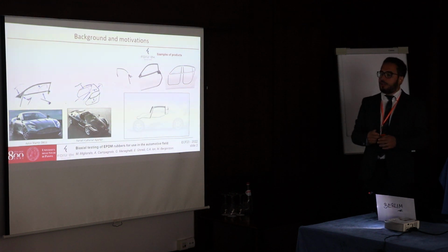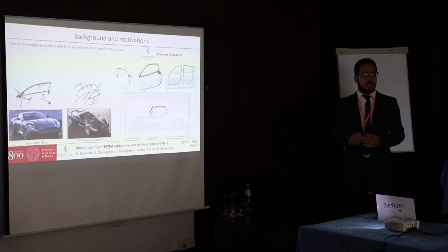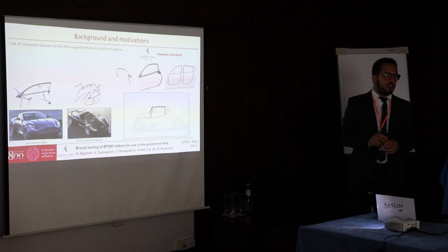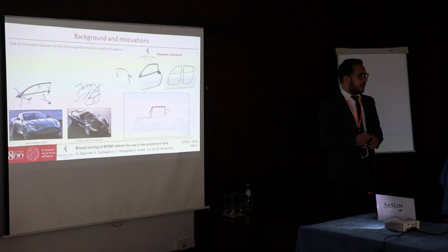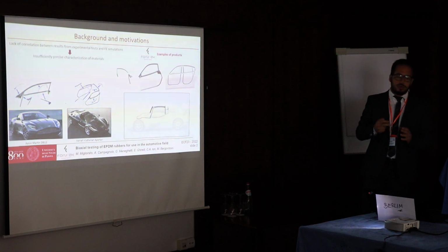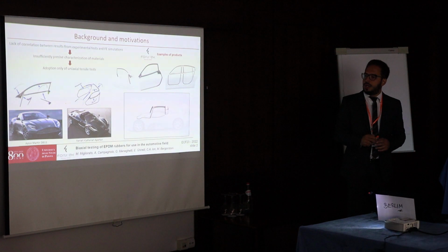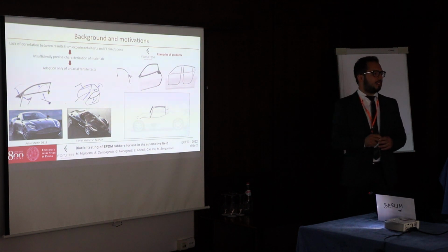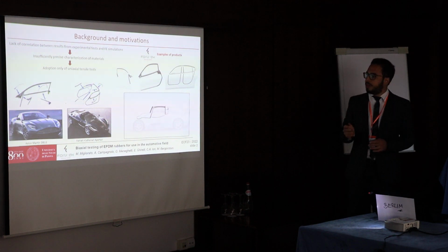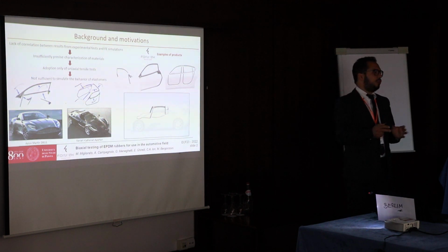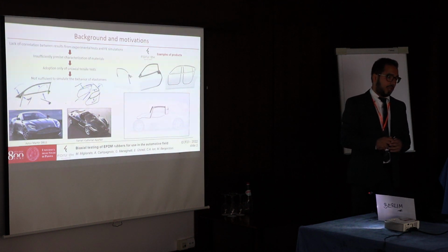trunk, and so on. Fornitec, during the design of such components, observed a lack of correlation between the available results from experimental tests and numerical simulation due to an insufficiently precise characterization of the materials. In fact, Fornitec has generated the experimental results by testing samples only under uniaxial loading. However, such a test is not sufficient to characterize properly the material under a generic stress state.